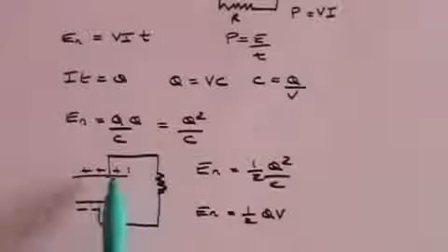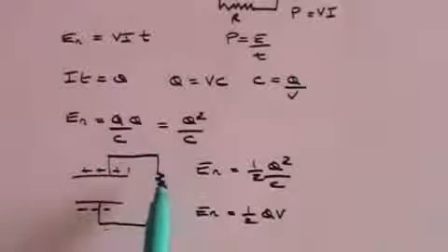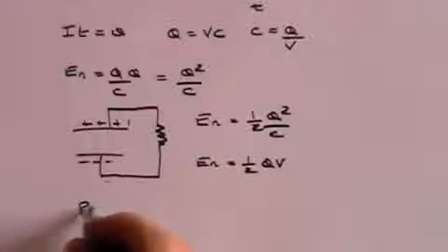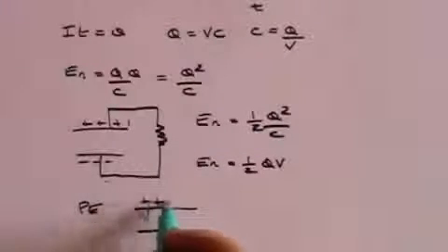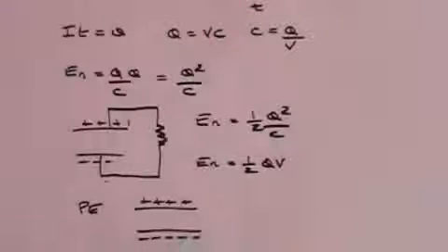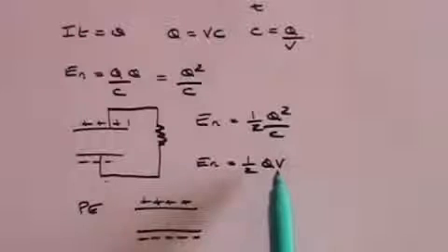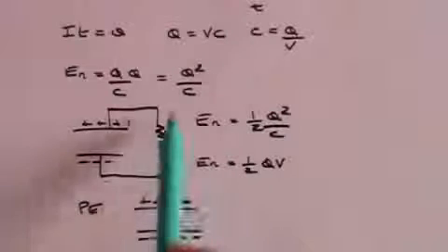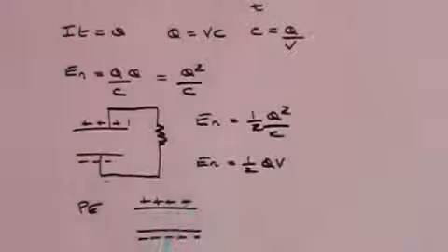And since that is the energy that is dissipated through the resistance as you discharge the capacitor, then it must also be the potential energy that sits on the capacitor, or is stored within the capacitor, before you discharge it. So when you charge up a capacitor, its total potential energy is half QV. And if you then discharge it, that energy will be discharged through whatever you discharge it through. So I hope that deals with the questions that I've been asked.